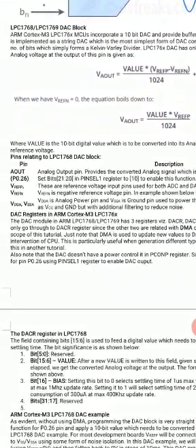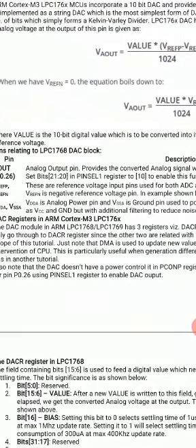Okay, so there are many others, like in the next lab you will study PWM. In PWM also, one pin will have the normal GPIO function, another function will be PWM, the third function can be something else, and the fourth function also can be something else. So here P0.26 was working normally like an LED, and now it will work as the output of DAC. To make this a DAC output, we have to send 10 to the 21st and 20th bits of the pin select 1 register. This is fixed, we cannot change this.